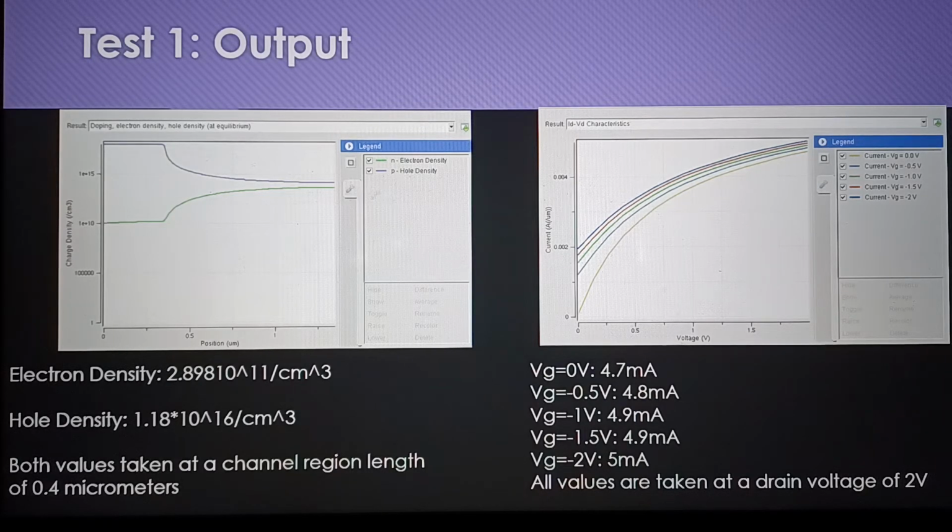So it seemed to have flipped from the baseline results to where the more gate voltage you put in, the more current that's allowed to go through. I'm also getting a lot more current that's able to flow through the device. So the flipping of the graph is, I'm assuming, since I changed the type from N-type to P-type, that's where I'm guessing the flip is from. As for the higher current flowing through the device, that has to be the change of dimensions that I've done.